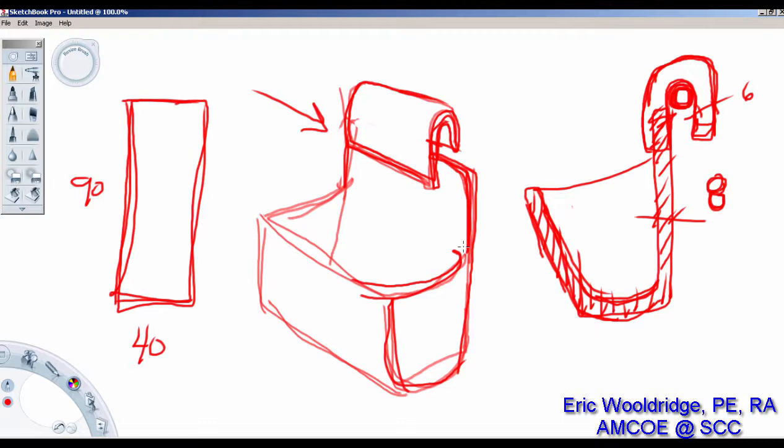This design may also be optimized for lattice structure design, but as far as this phase of it, we'll design it just simple and straightforward. We'll also use a different approach. Instead of using a lot of dimensions, we'll design it for sort of a dimensionless approach. We will at least model what the bar of soap size is and the wire or the frame that's going to hook over size is, and the rest of it we're just going to kind of freehand, given the advantages of using an organic design approach with additive.